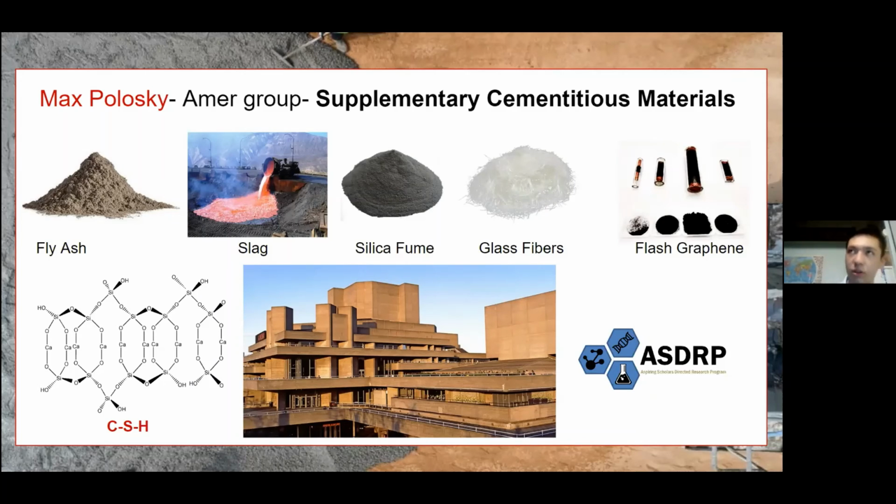Another very promising alternative to SCMs is geopolymers. Geopolymers, in theory, can completely replace cement in concrete if a very basic solution is mixed with a source material containing alumina and silica in a certain way. And for this reason, that is being researched very heavily. But the reason this is not used is because very basic solutions are difficult to use on job sites. And so geopolymers are suboptimal for large construction projects.